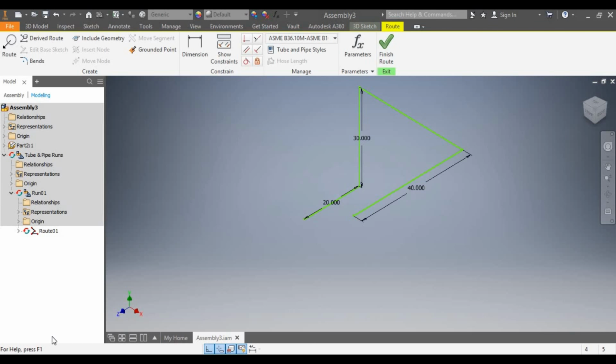Suppose we select a sketch 2 inch in X direction and 2 inch in Y direction and apply it to a 2 inch pipe of any spec. Here we should consider that your selected or drawn segment length should provide radial length for elbow, T and other fittings. I will explain this error at the end of the video by example.